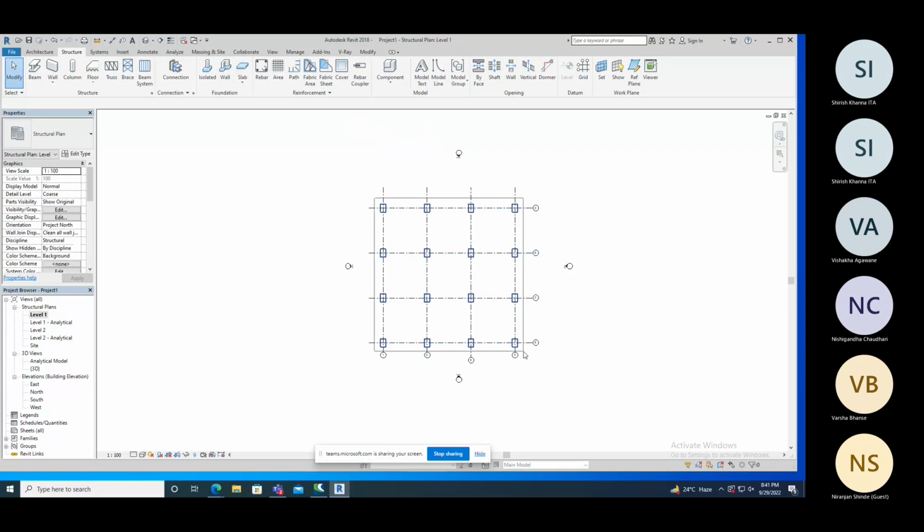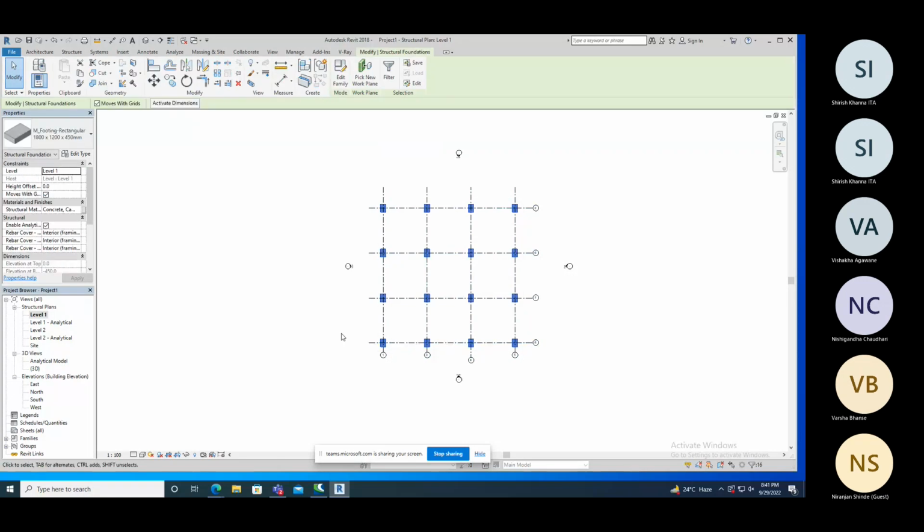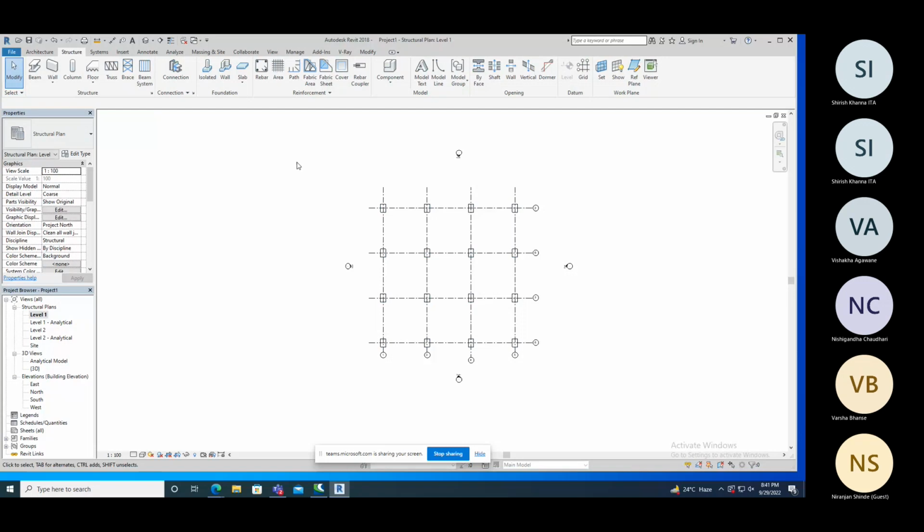Let's select all the system. Now I'll tell you one more thing here. Let's suppose you want to move these four, so you can select from left to right. Which portion is under this box, that is only selected. If you are taking from right to left, then see grids is also selected. It means intersection also selected. So which is fully enclosed, then you have to select by left to right selection.